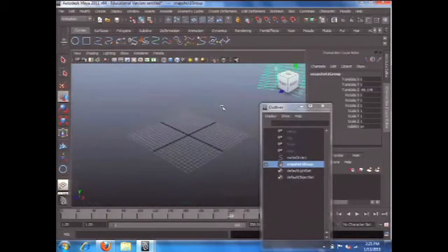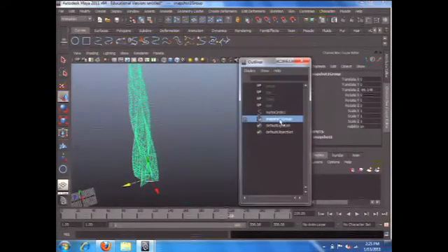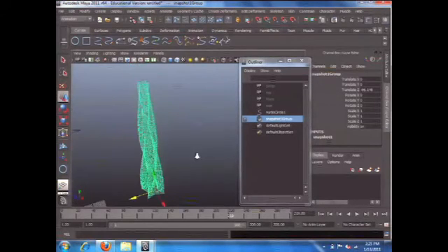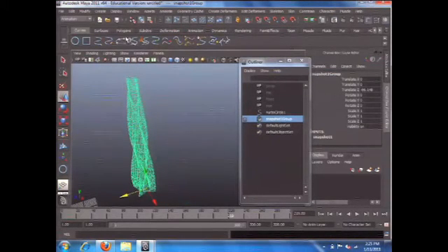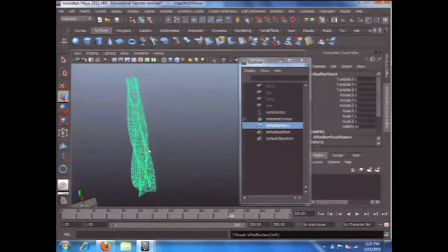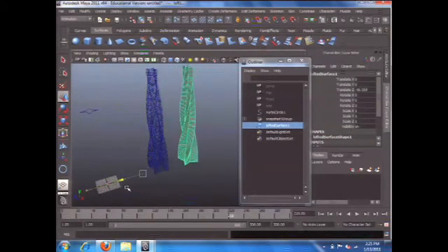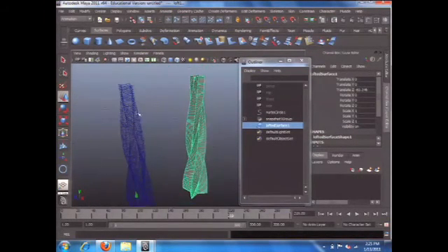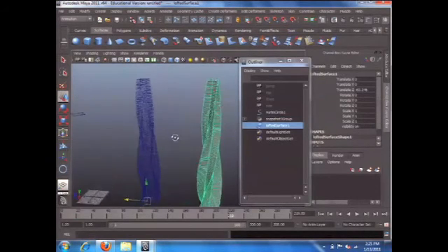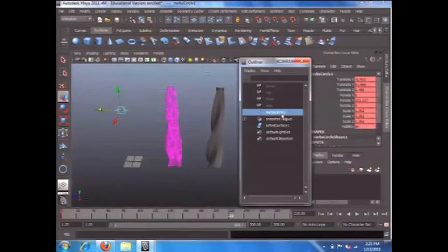Then guess what? I'm going to do the skin. I will select all the lines in that snapshot and do a loft. So Surface, Loft, right? You can create a skin. Just make sure you move a little bit. So you can see this is the original curve, and this is the skin from that curve. And everything is controlled parametrically from the original animation.